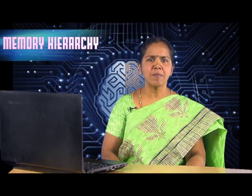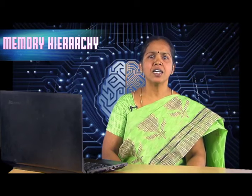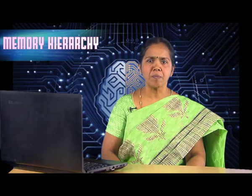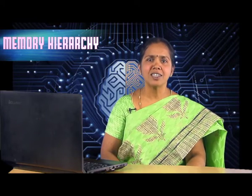EPROM. If a PROM has been programmed and has an error and needs to be updated, then the chip has to be discarded and a new PROM is created to replace the old chip. It is an EPROM, that is erasable programmable read only memory, which is a PROM that can be erased and reprogrammed without being replaced. EPROM is a special type of memory that retains its contents until it is exposed to ultraviolet light. The ultraviolet light clears its content, making it possible to rewrite the memory.